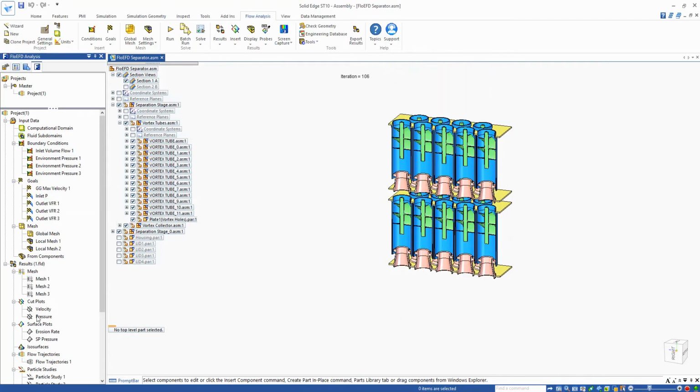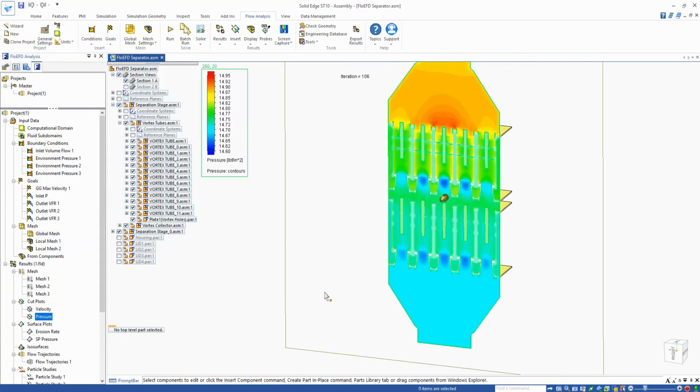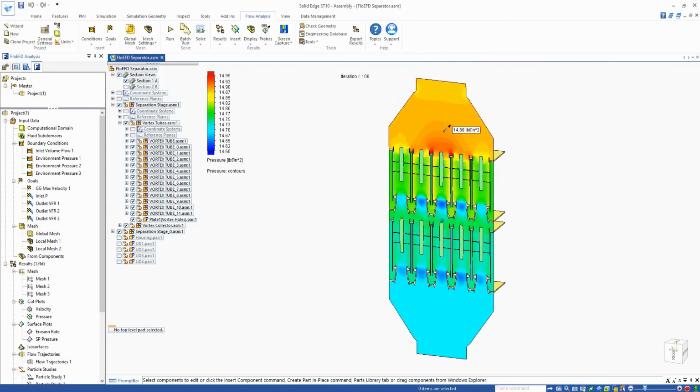We can also have a look at what the flow pressure looks like. So to maintain that 100 CFM, what's the delta P got to be? Well, we can see the inlet pressure and the outlet pressure, so maybe 0.18 psi or so upstream pressure required to maintain that 100 CFM through the unit.